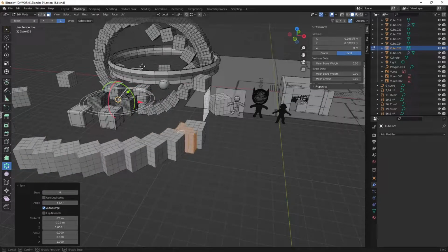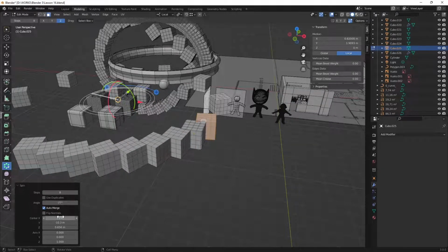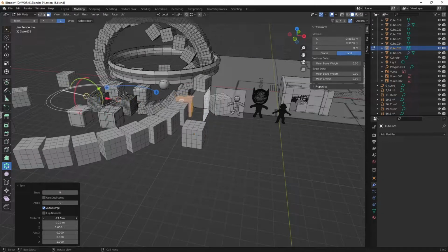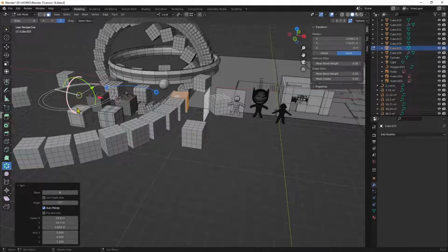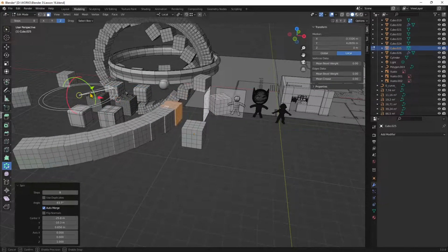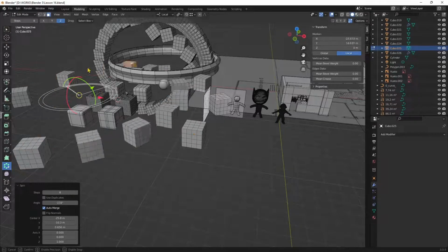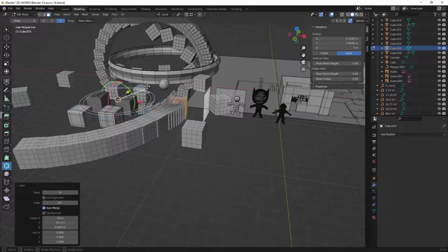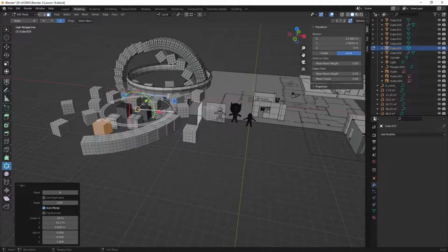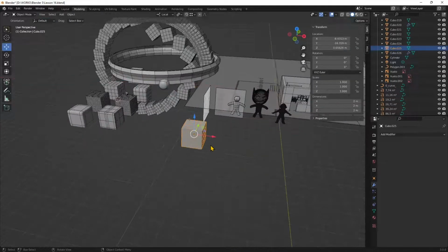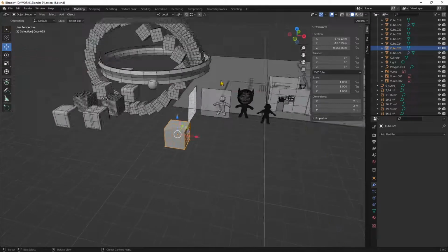Now if I click again, it's gonna create more, and then I can change the center a little bit, so to create kind of a spiral. And again, you can continue, adjust it, and do it again, and so on. So this is how you can multiply. It's similar to the sequence, but this time it's radial, and this is called polar array in other software.